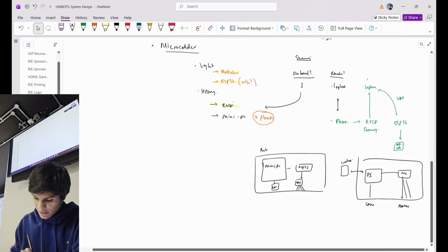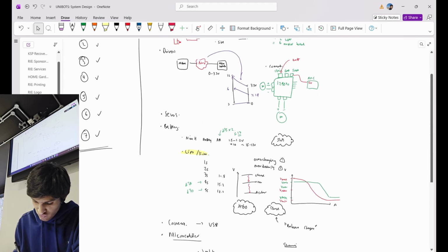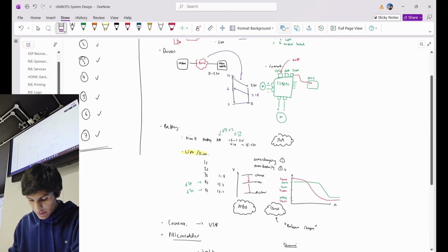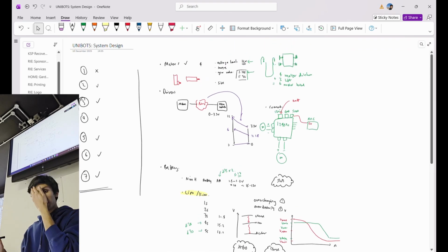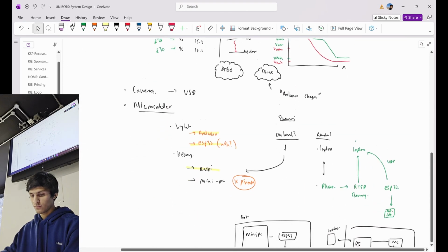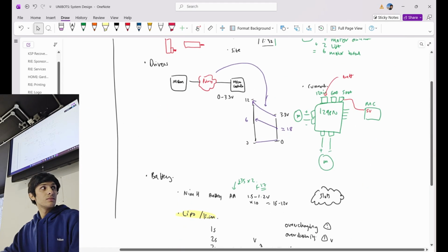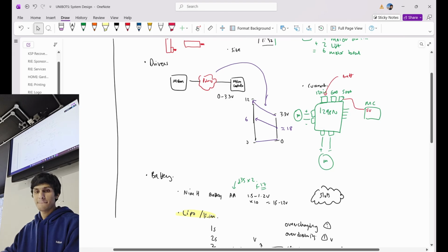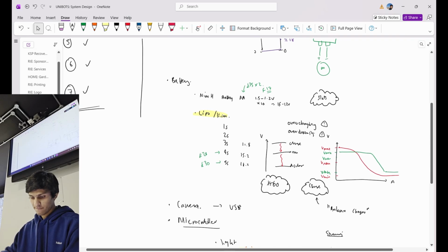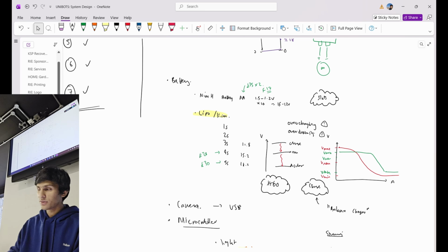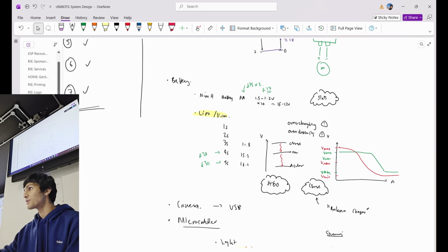Lastly, servos. I do want to add a safety consideration. With GPIO, it's really important you always go directly to a motor driver. GPIO pins, by design, are only for little things that go back and forth. They only work at a certain current level, and these are small traces on the PCB that can burn up easily. We've burned a Pi before, so don't burn a Pi. The Pi was £70, so don't burn a Pi.